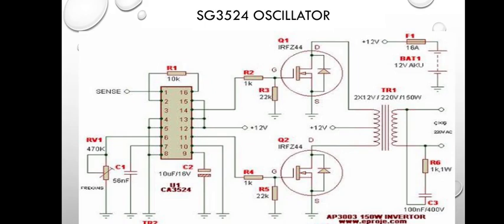So pin 1 is for feedback, then pin 2 is a reference voltage. I told you it is an operational amplifier. So the reference voltage is referring the voltage coming from the outside to the pin. So it will be using pin 2 to correct the pin 1 voltage. Are we together?